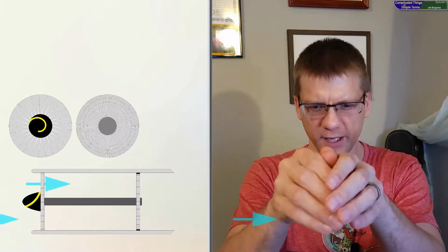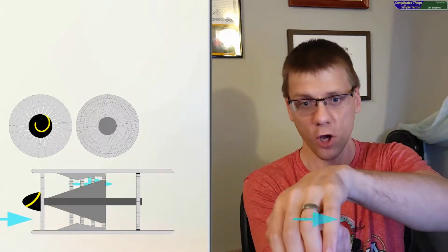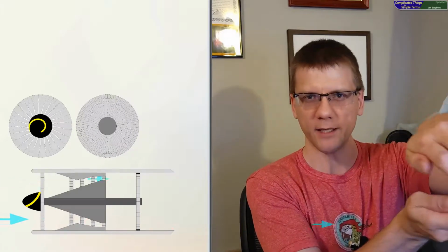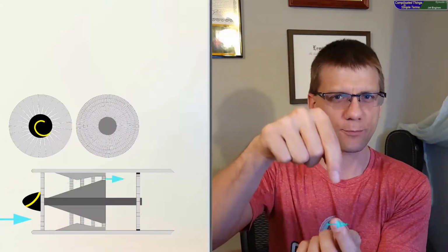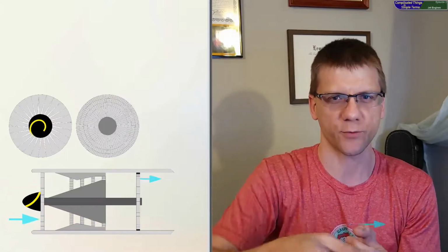There's actually sort of a conical structure, although it's on its side, and this conical structure, this cone, gets bigger as it goes back into the engine. And the fans that are built around that get smaller and smaller and smaller. So they're little rings of fans with a big hub at the center. But notwithstanding the geometry, it's just a series of smaller and smaller fans that force the air into a more compact volume of space. Well, when the air gets compact, it also gets hot.